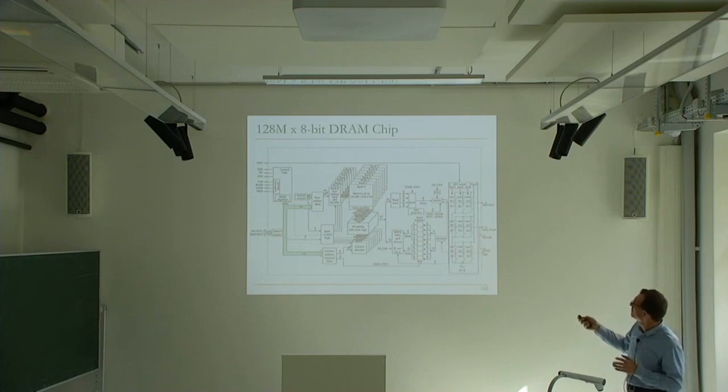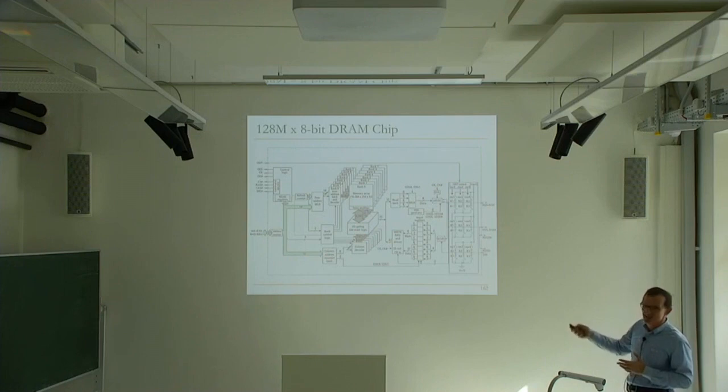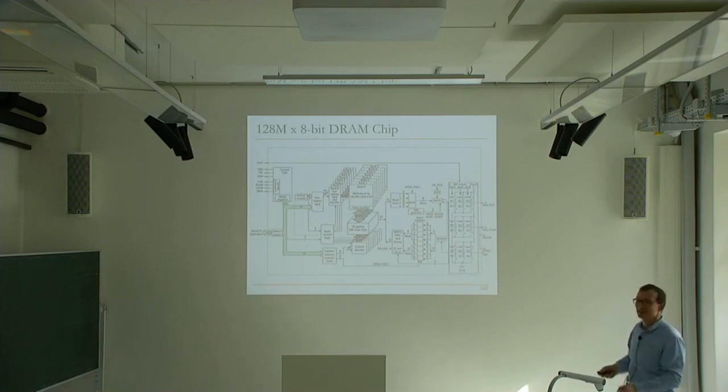Even though this is an 8-bit chip, you see that you're reading 32 bits of data, actually. So they're doing a lot of internal prefetching of the data into this read latch. And modern DRAM has what is called burst mode. The first read, you need to wait for some time. That's the first 8 bits. But if you're reading consecutive 8 bits, you can get them very quickly because of this internal prefetching. So you actually read 32 bits. They give you only 8 bits in a cycle, but you can get the next 8 bits very fast, next 8 bits really fast. This is called burst length. So modern DRAM can give you essentially a single cache line worth of data within a burst.